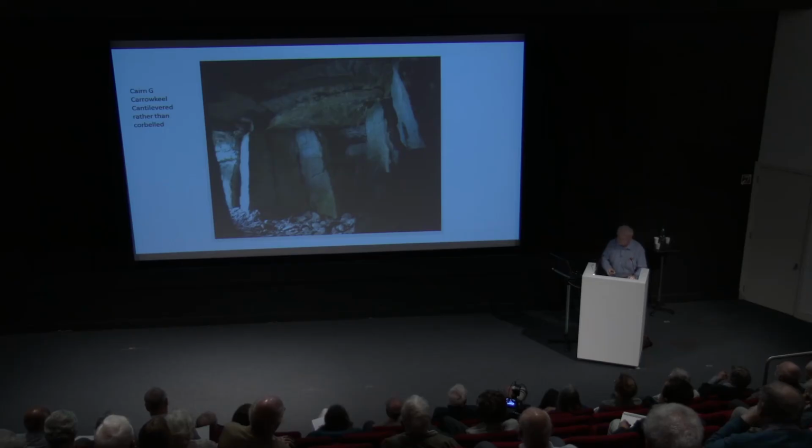That cantilevering effect that was in the last sketch is where you have the lintel that goes out over the edges, and the weight there is pushing down and sort of providing some uplift against the weight that's pushing down there across the major span. I think that may be what's being done in this group of cairns in Ireland called the Carrowkeel cairns. I have some blurry photographs of them, and I did spend a day rambling around them. But I'm not confident enough to assert firmly that these guys are using cantilevering rather than corbelling to achieve their roofs. But I think that's what they're doing.